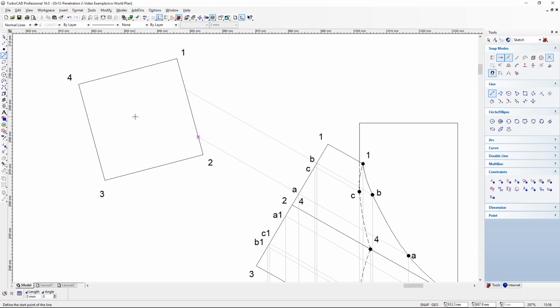Because we're viewing the auxiliary view at an angle of 90 degrees, we know that the distance that I measure from number 1 to this point, let's label them so that we can use a proper reference. So that will be B over there, because it's the projection of B onto the auxiliary view, and then of A onto the auxiliary view. So now we have point B's true length from number 1 in the direction of segment 2. So from 1 to 2, I have B and A.